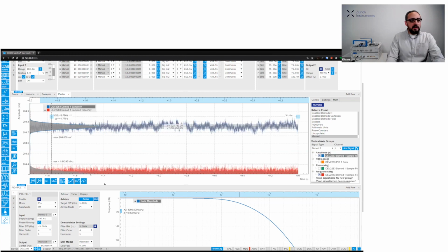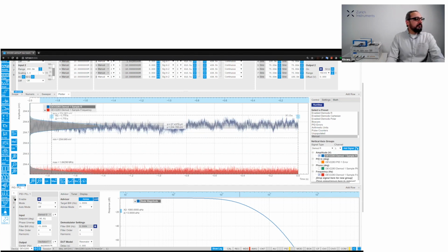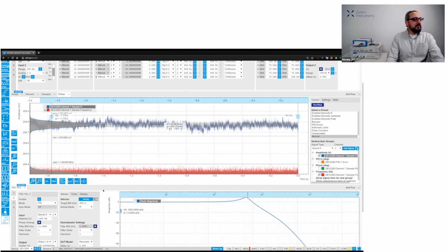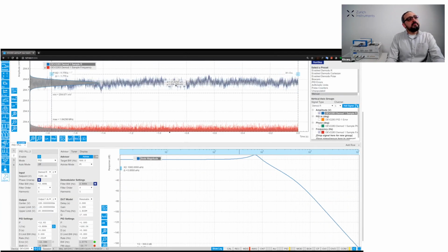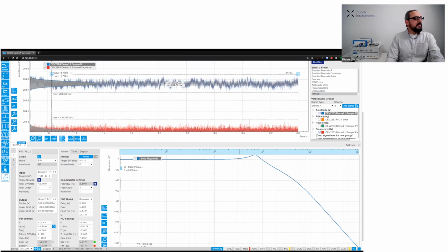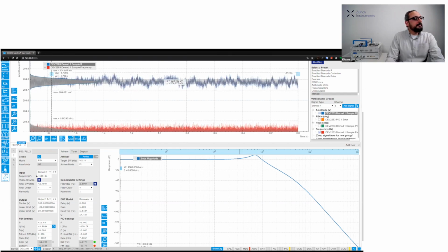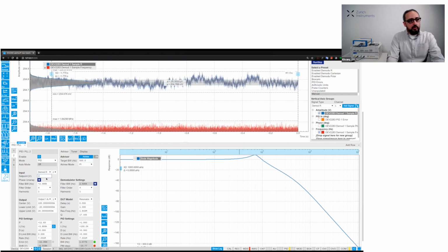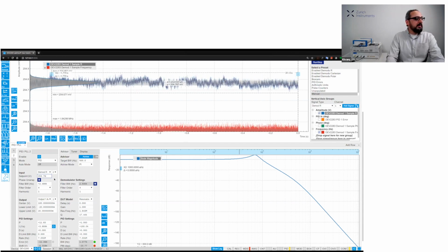So this is the amplitude gain control that I was mentioning before. For this, I will grab the second PLL. And in this case, now we have an amplitude around 204 millivolts. So let's aim that as a set point, and we will be looking at this value directly. So it is 204.7 millivolt as my set point.